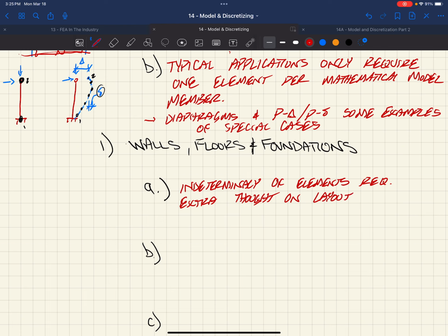Stiffness attracts loads. So depending on how we discretize things, we're going to affect how load is transferred throughout the system and where the stiffnesses are located. You can imagine if you had one big element for the entire floor level, that's going to be a bit stiffer than if we were to break that one floor level of Cobley Hall into 10,000 elements, right?